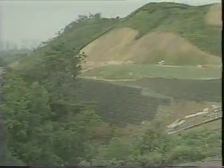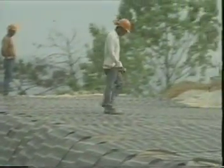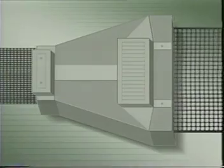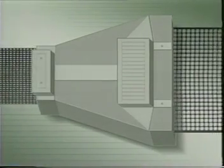Consequently, most geogrids are drawn in one direction and are said to be uniaxially oriented. These are suitable for reinforcing walls or slopes where the principal reinforcement is required in a direction normal to the line of the face. Biaxial polyethylene geogrids are formed by heating and stretching in two directions. These are used where axisymmetric loading may occur, such as in the reinforcement of roads.